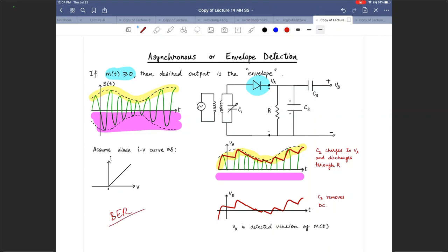But in general, if I was talking about bit error rate for wireless transmission using asynchronous detection, I would assume any value between 10 to the negative 3 and 10 to the negative 6, which means one error in 1000 bits or one error in 100,000 bits, 1 million bits. So that would probably be my first guess for asynchronous detection for wireless transmission. It depends on too many things. It depends on where your phone is in the room. For example, if you move around in a room, your phase diversity changes, and there are too many underlying things for me to be able to quantify that.